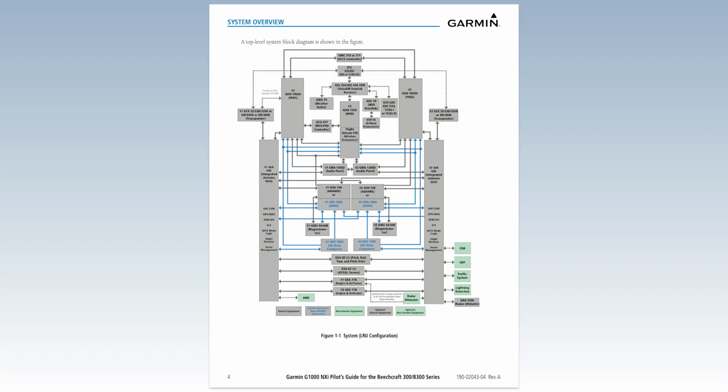The foundation of the autothrottle system is the Garmin Integrated Avionics Units, or GIAs. The GIAs receive engine data, ADAHRS, and AFCS inputs. They then interpret this information and send the appropriate commands to the autothrottle servos to move the power levers in accordance with flight director guidance, in relation to airspeed, attitude, and altitude.